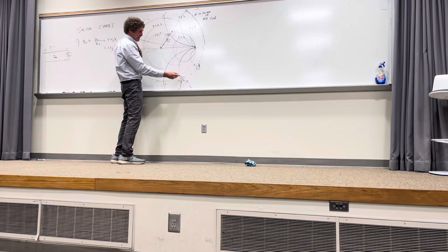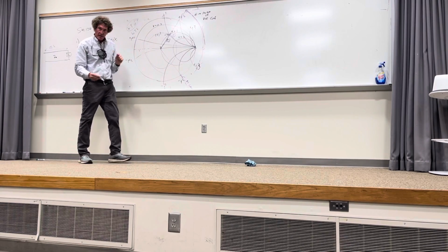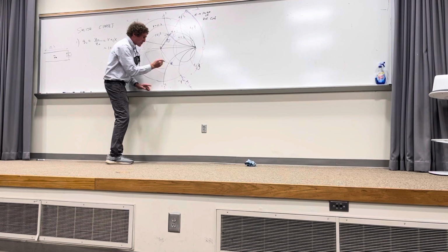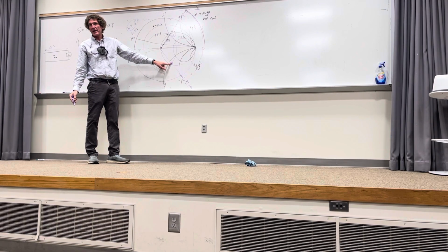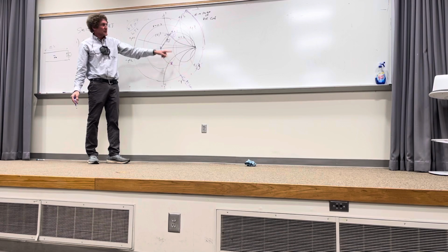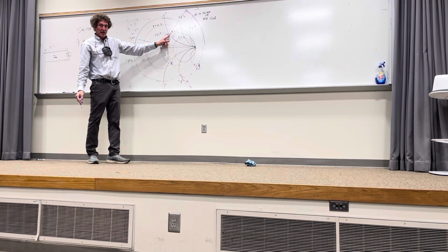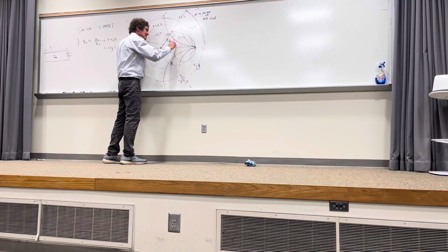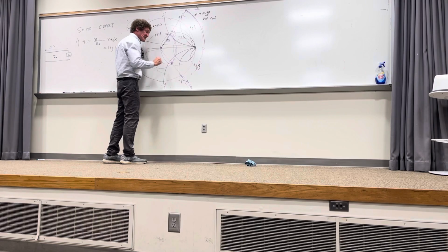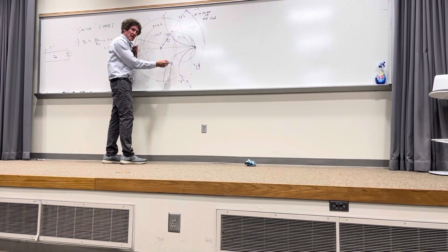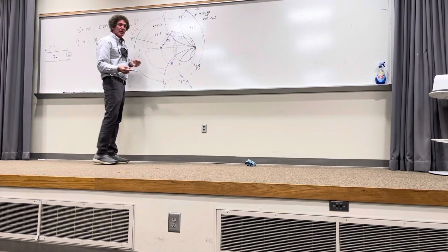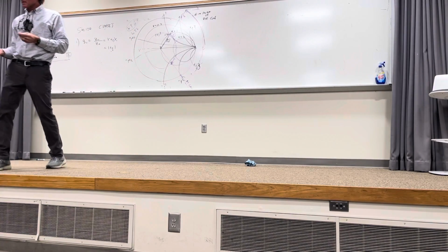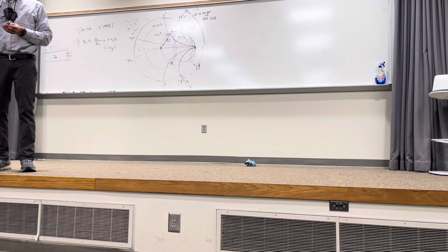And now the only thing I do when I find this is I take my straight edge, draw through there, and then I'm going to have a point where I have a new value of R plus jX. Do y'all hear me? This one was 1 plus j1. Now I moved, and technically the way they show it a lot of times is this. You're moving along this trajectory until you move the length of the line. Down here I'm going to have something else. I'm going to have a real and imaginary part that are going to be quite different than my original. Then to get the actual value of the input impedance, you multiply it by Z0.